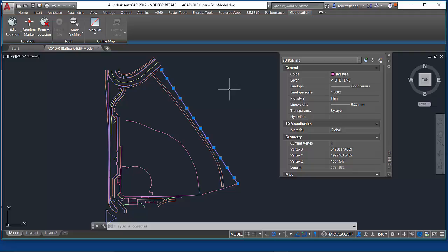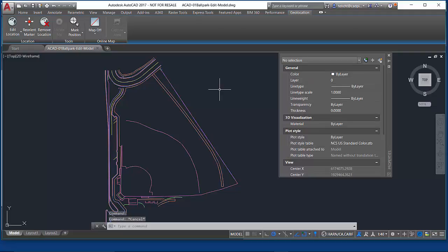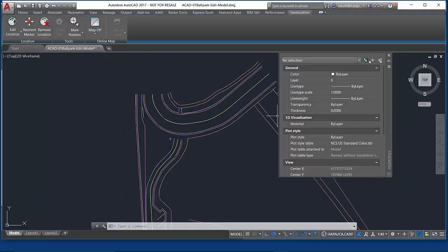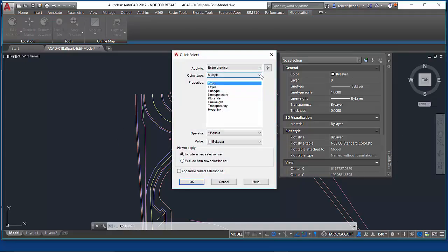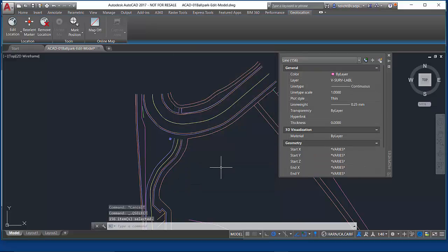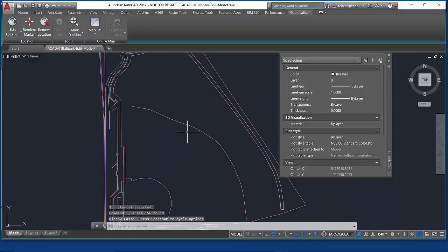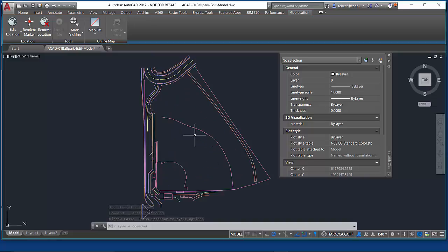However, there's some other issues here, since when it goes out to AutoCAD, you may, and we'll just zoom in here, you can see that we were using markers on some of our figures that use PDMODE markers, so those will end up with lots of little lines. So one of the things I probably want to do to clean things up here is grab all the lines, select all of them, include those in a selection set, and simply delete them. So now I've got rid of the hanging CADs out of my figures.